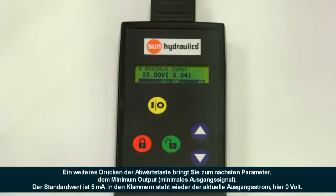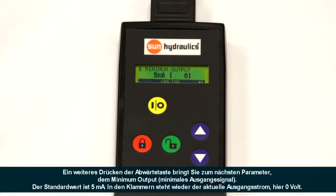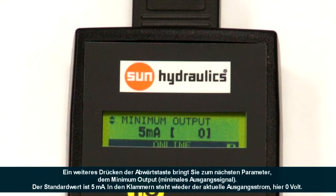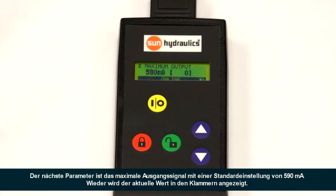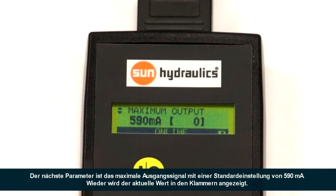Pressing the down arrow again brings you to the next parameter of minimum output. The default value is 5 milliamps. Again, the value in the parentheses shows the actual current being supplied from the amplifier at the moment, 0 in this case. The next parameter is the maximum output with the default setting of 590 milliamps. Again, inside the parentheses shows the actual output current.